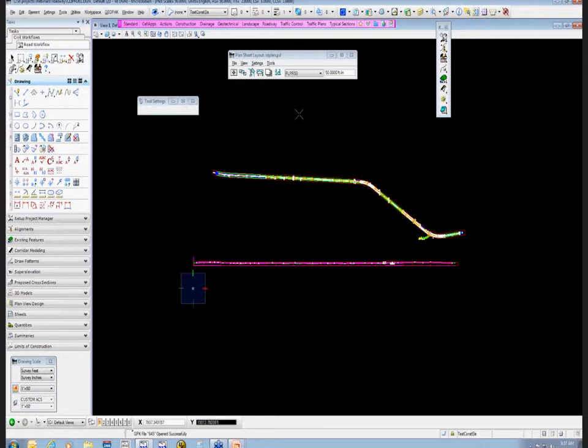And if you ever get in there and you get a huge number of sheet borders that it's creating, most likely what you need to do is go back and look at, did you set the scale before you went to put your borders. I've seen that happen. So just go back up, delete the borders, or don't click to create them in the first place. Change your scale, and then they'll come in right.